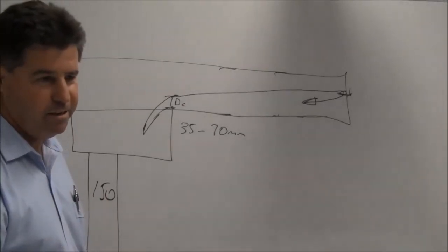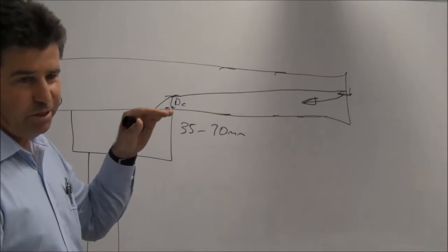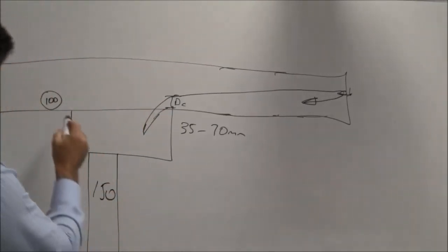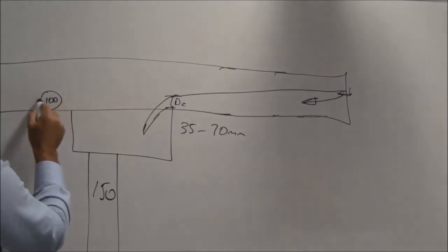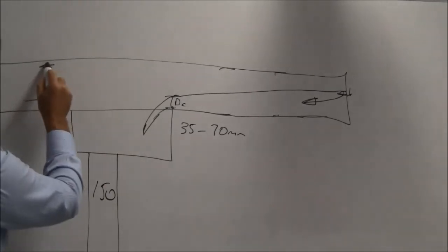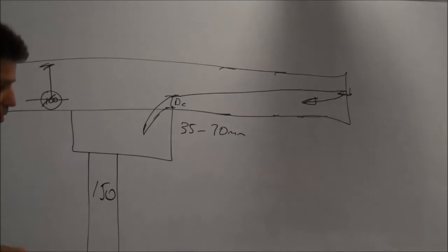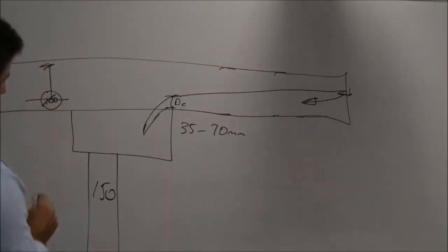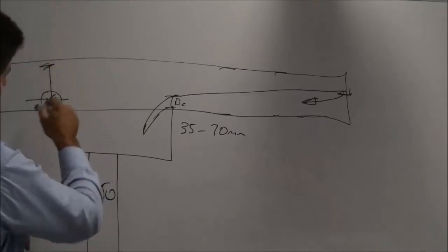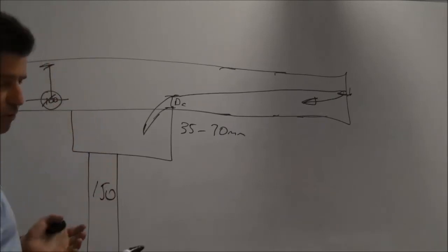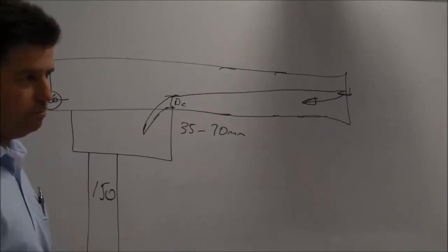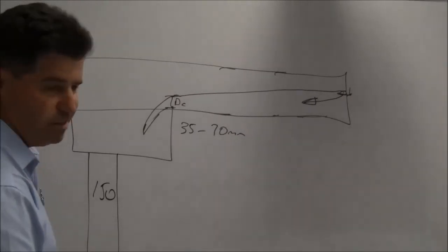Now, unless that gutter is very, very deep, the amount of water you're going to get, I mean, that's an orifice calculation. So from the centre of there up is the head of water that you need to drive it through. For that type of overflow to work, you need a lot of head to force it through to be equivalent to the amount of water you've got flowing down the downpipe. Otherwise, it just won't work. Or you're just going to flood the place. And that's your insurance on the line.